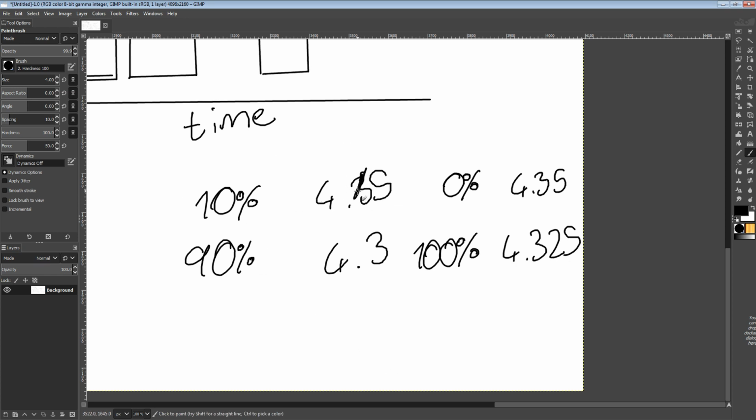Or let's say 4.45, to make it look like we're overclocking, so let's just whack 100 megahertz on top of everything. This isn't stable, but it is actually faster, because in order to get an average frequency of 4.425 gigahertz, you'd have to be spending 50% of your time at 4.45, right? Which you aren't. So this is faster and more stable.